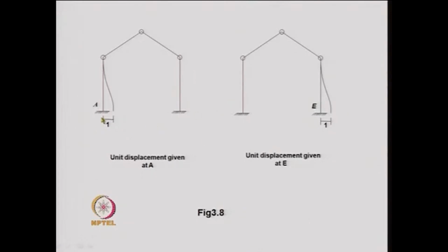And this is how we obtain the R matrix. If you recall, we give a unit displacement over here and find out what forces are developed here and here, that gives the stress stiffness matrix, and from that one can obtain the displacements caused at these points due to the unit displacement.